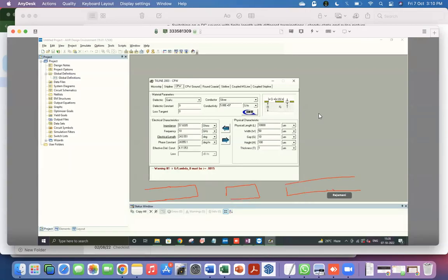And let me draw the slot line at the top. The point I made about the vias and the air bridges, that the two sides of the ground plane for a CPW have to be at the same potential, is precisely to prevent the propagation of signals via the slot line mode.